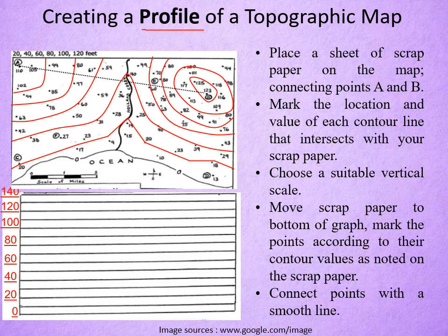So if someone gives you this kind of topographic map having different contour lines, having spot elevation points at different areas, having a fixed scale, indicating the geographic north, and the contour line values are also given, that is they are in feet, with a stream flowing in between, as here it is a V of contour line and the tip of the V indicates the upstream side.